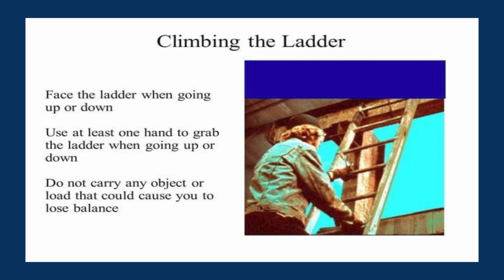Climbing the ladder. Face the ladder when going up or down. Use at least one hand to grab the ladder when going up or down. Do not carry any object or load that could cause you to lose balance. Always maintain 3 points of contact while ascending or descending the ladder.